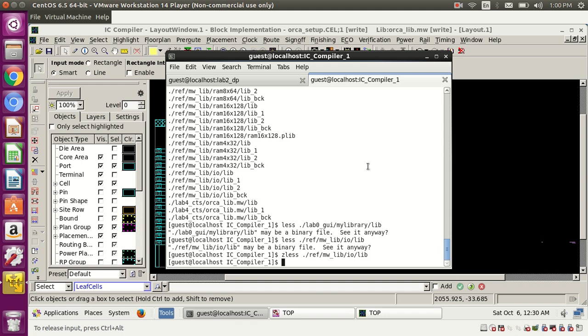But for the flops, the clock input changes every clock cycle, and the time period is in gigahertz, we are doing 3 gigahertz, so that many times per second it will switch. If that goes on for 1 day or 2 days, that chip may get damaged because of that power. Whether it may damage or not, that's okay. So every clock switching will take some power, but there are some cases where the data input may not change, the input may depend on some other cases.